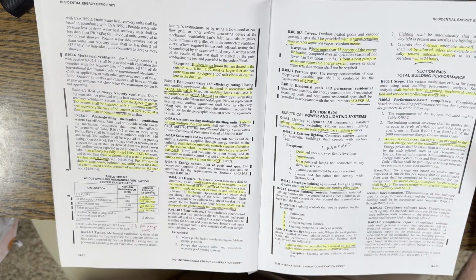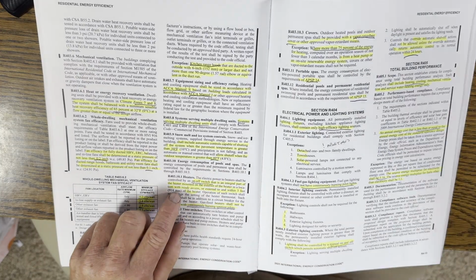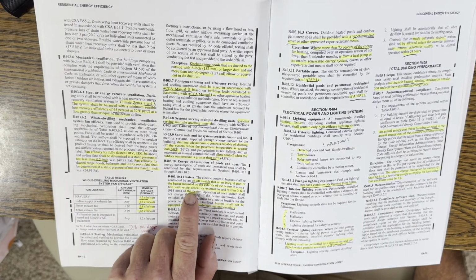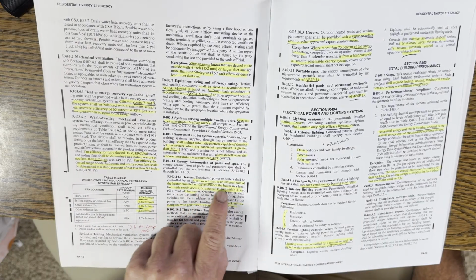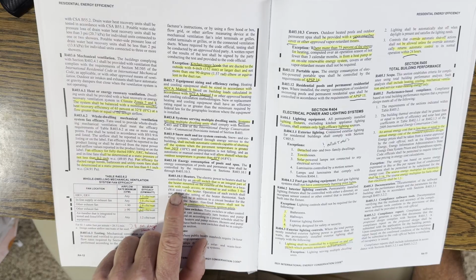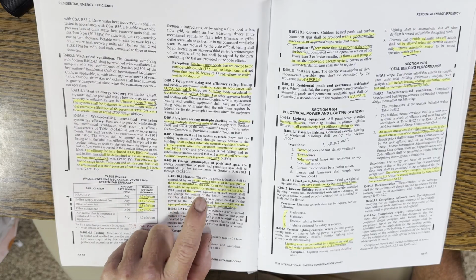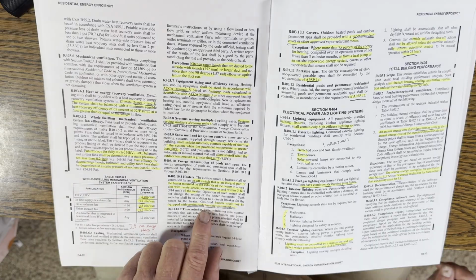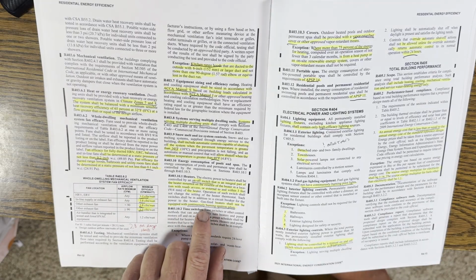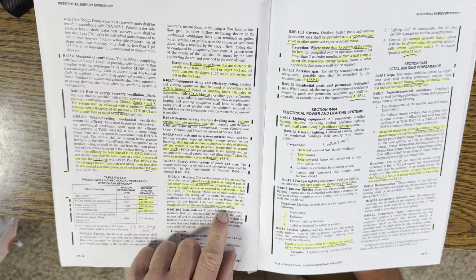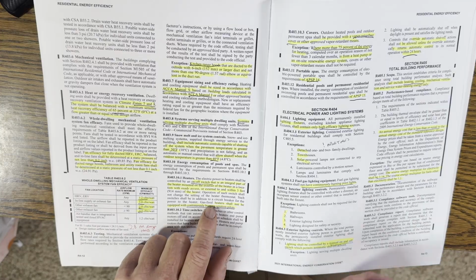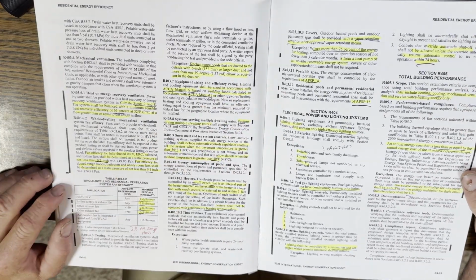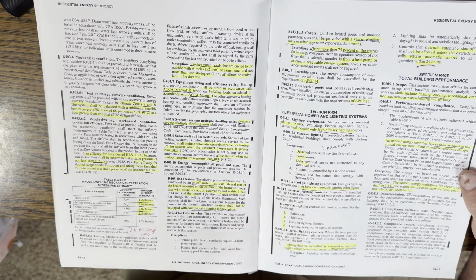You had a question on pools and spas. You had two questions. So the answer was readily accessible. So the on-off switch that is an integral part of the heater for this pool has to be within ready access. So that was the answer for the particular one. You had another question. Heaters, they can't have continuously burning ignition pilots for pools. So that was another question I was asked on this. Oh yeah, and then, no, it wasn't that one. There's another one. Never mind.